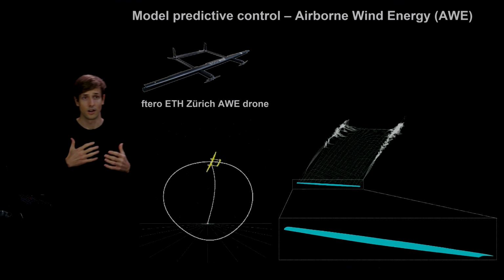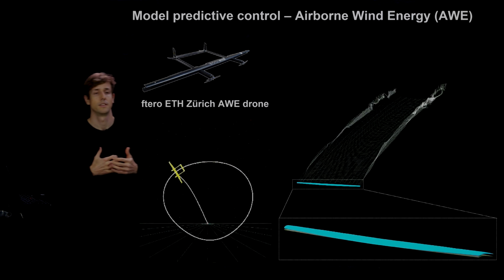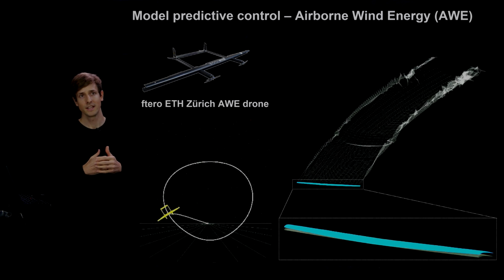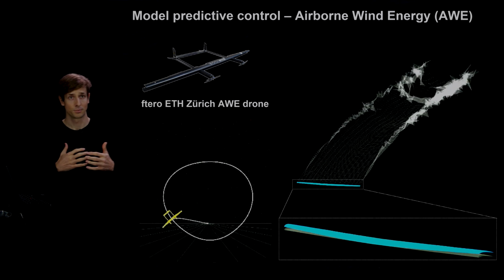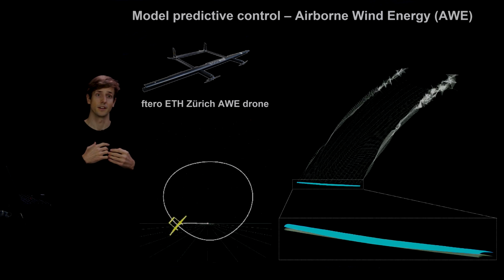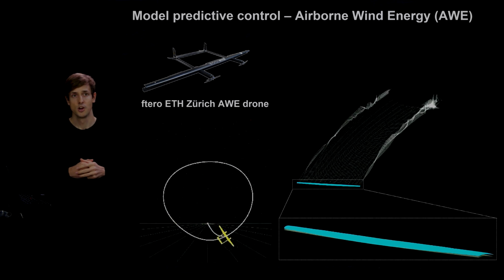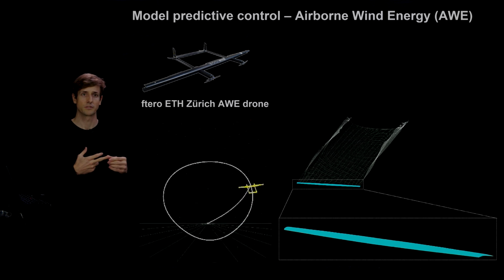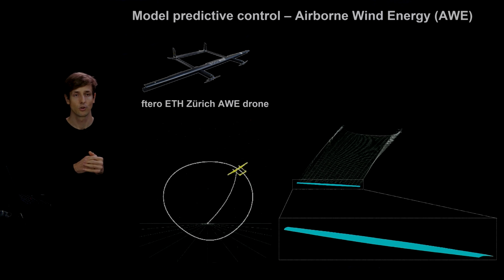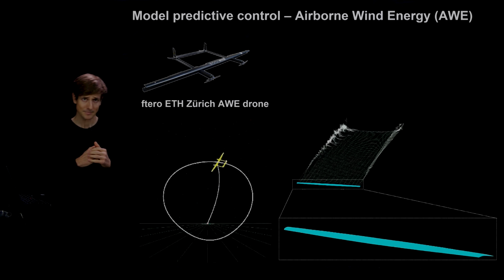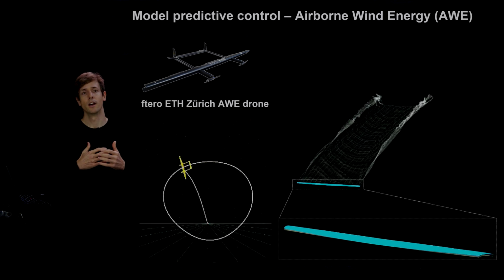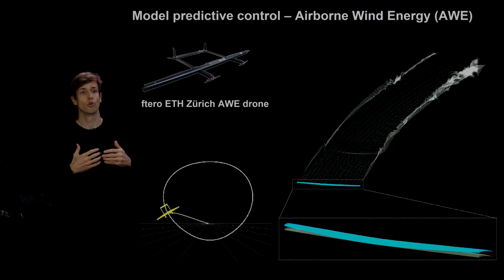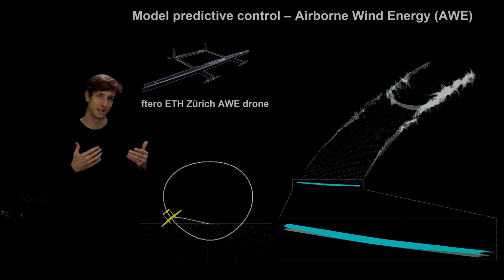So then last, to show the performance of our modeling approach, we incorporate the ADMDC model into a model predictive control framework, and we run several control examples. For example, we try to mitigate gusts, or we try to follow a specific lift coefficient trajectory. And then ultimately, we want to use our ADMDC model to control the loads on an airborne wind energy drone.